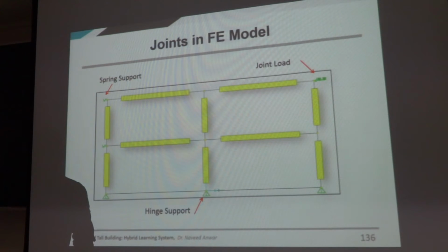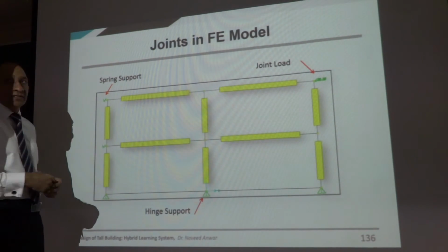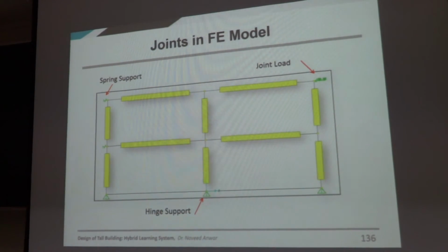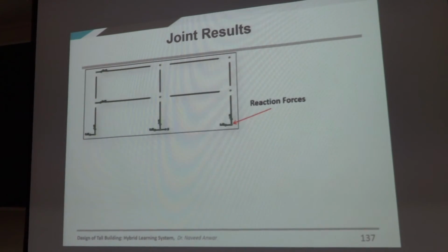It's very complicated to model the interaction between structure and soil. And an earthquake is very different. At rest, the structure is at rest, but when you apply the wind load or earthquake load, the structure is moving, it's hitting the soil. So what's going on now? These are complex issues which still need to be considered, and sometimes we just ignore them and simplify them.